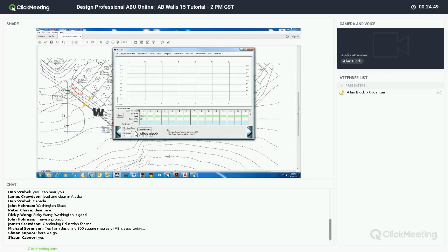If you have a tall wall, you're going to follow those rules, but if you have a slope below the wall, you may have to adjust for what we term a 5-foot benchmark from the toe of wall to the crest of slope. If you have any questions on that, we can certainly provide you a schematic of what we're talking about. Sometimes people have a different terminology.